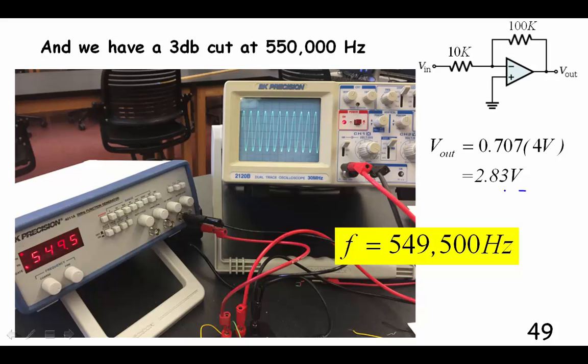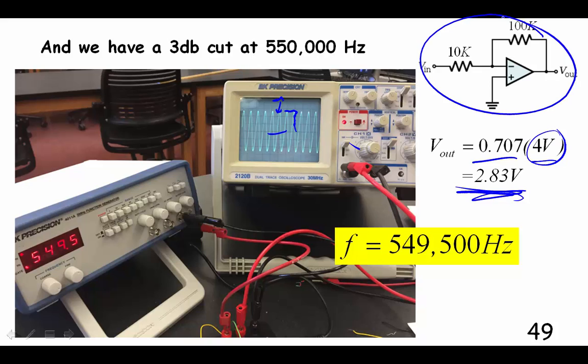Oh, we're at the minus 3 dB point, so that is 3 decibels. We're multiplying the 0.707 times 4 to get 2.8 divisions and it's at 1 volt for our output. So there we are at our cutoff frequency of the op amp itself, even without any kind of filter.